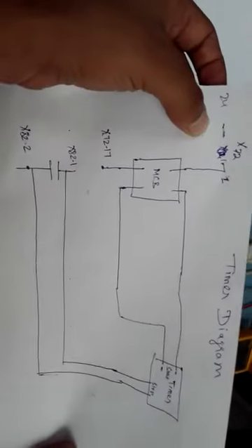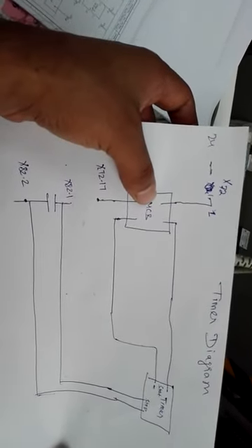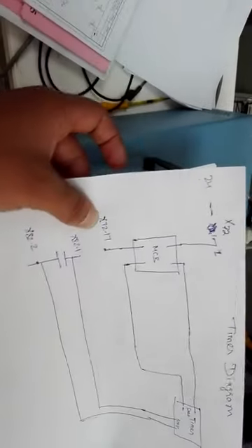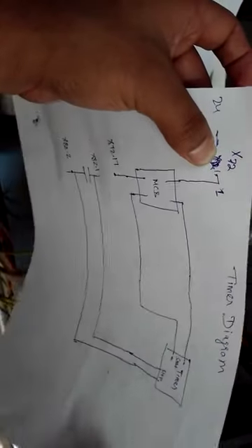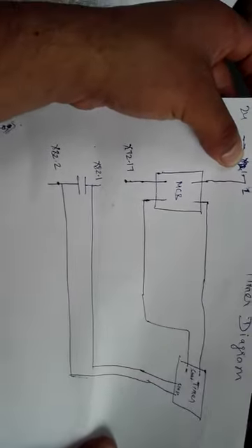So now I will show you here in the timer. See, this is a connection which I made X72.1. Okay, so it will go through my MCB and then it will be connected to X72.17 for channel 1 or for window 1. Then I will keep this point same, because it is common, provided to all the circuits of annunciator or all the channels of annunciator, I would say.